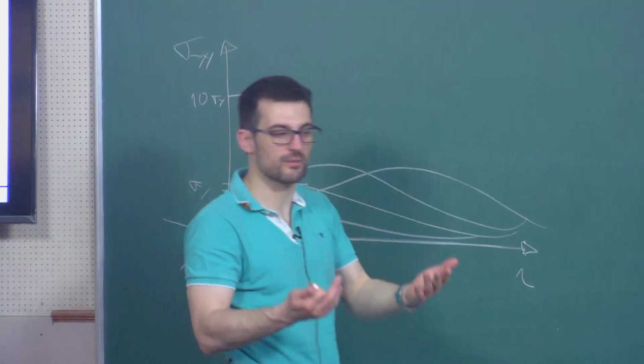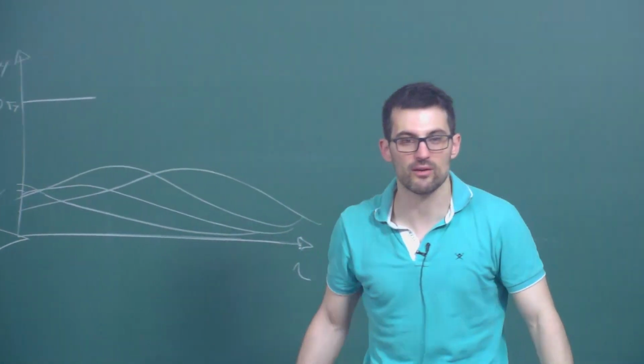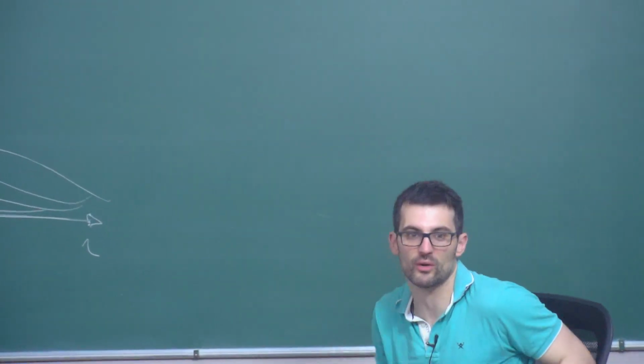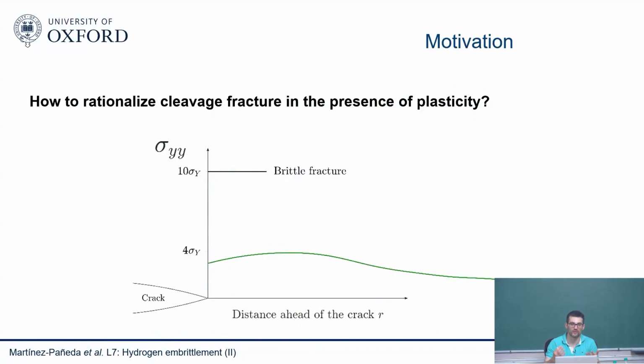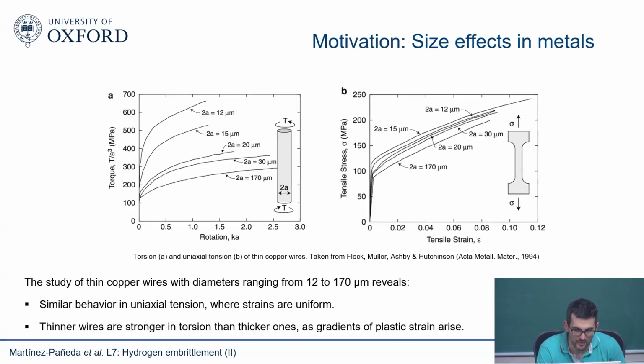More plastic strain-driven failure mechanisms take place, like void growth and coalescence. This is the issue. So this is quite common, I think, used in the automotive industry. Sometimes they look at cleavage versus ductile fracture, and they have basically rather simple models which are based on a principal stress if you have some sort of cleavage fracture, or an equivalent plastic strain if it's based on some ductile fracture mechanism. So this is what happens.